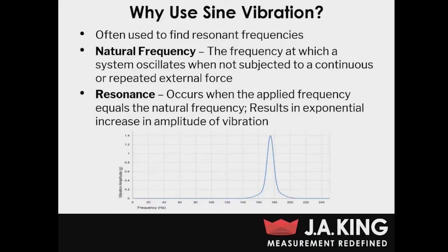You can see as the frequency increases and you do hit that resonant frequency, right at about 175 hertz, you get a huge spike in your vibration amplitude. So looking at this graph, you would know that the system you're testing has a resonant frequency of about 175 hertz.